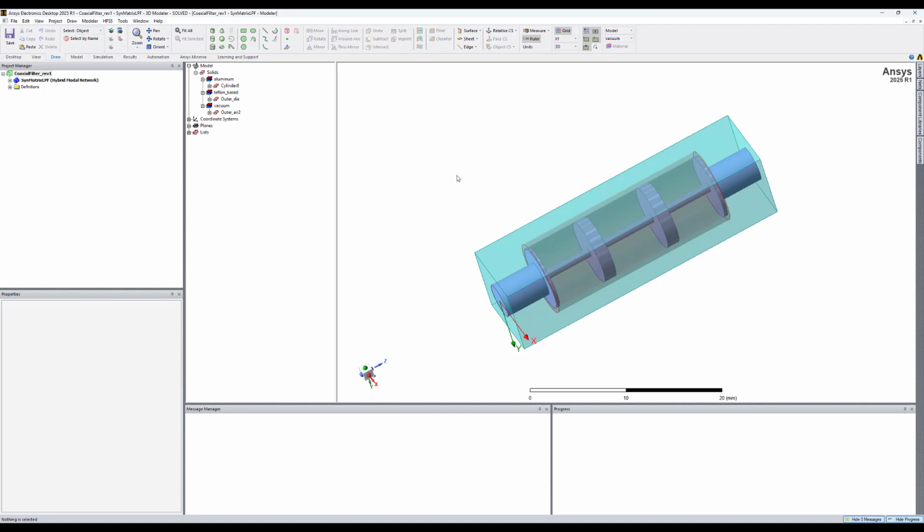In this demo, we will be using ANSYS 2025 R1, and I will show you how to do the one-way coupling between HFSS and Icepak, where we pass the EM loss to the Icepak design to run the thermal simulation. I will demonstrate two approaches to set up the Icepak simulation. The first one uses the automated workflow that has been added recently, and then we will set up the Icepak simulation through the manual approach in a step-by-step manner.